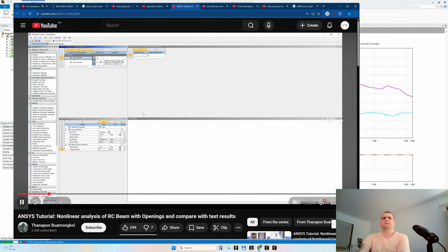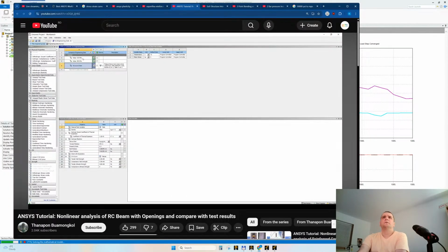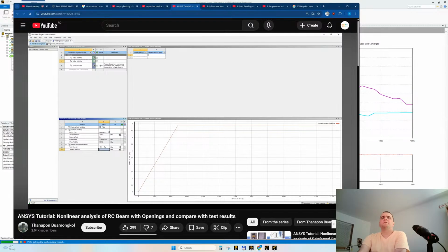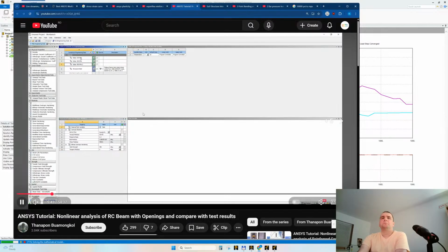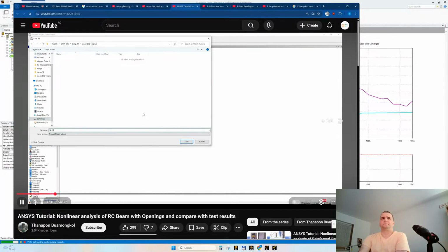With Bilinear, yes. Tangent. What? Come on, don't leave tangent modulus 0. It will be perfect plastic, no? If you leave it 0, it will crush very soon, let's say.